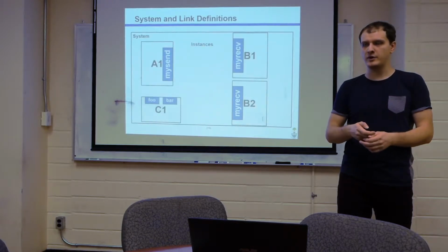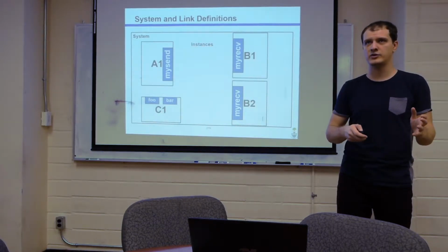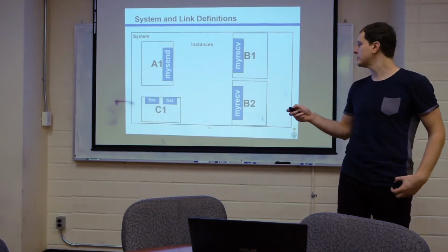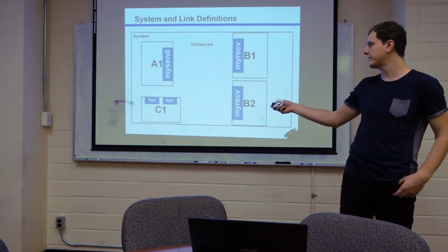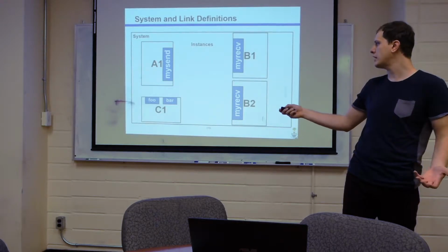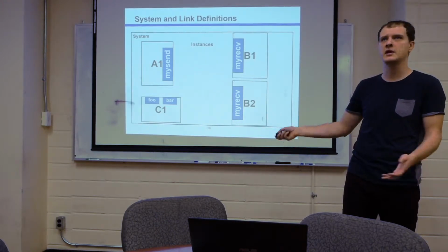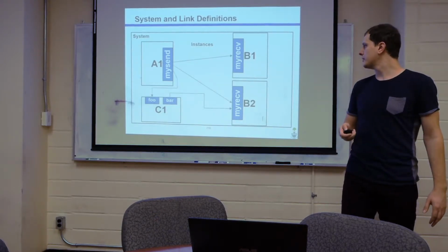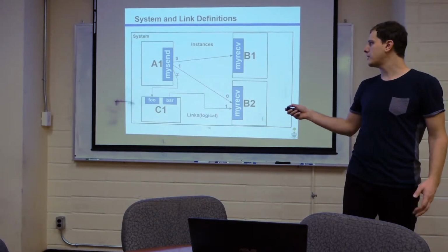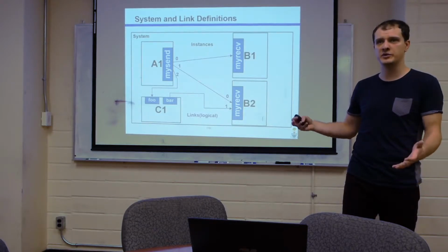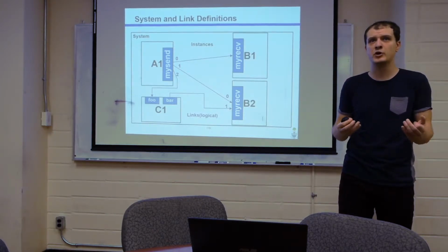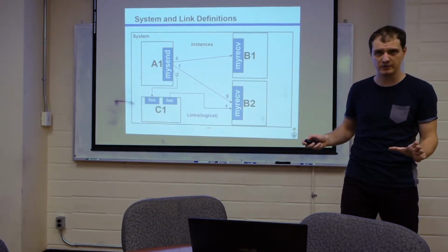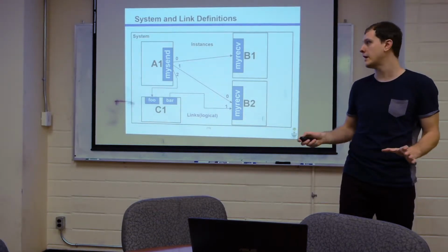Okay, so you define your modules and your interfaces, of which the RS ones are the interesting ones. You define your system, which instantiates the modules, and create logical links between the interfaces. I'm only showing routed streaming interfaces here because those are the interesting ones. So you define links, and optionally, this is when you assign addresses. In Genie, addresses don't belong to a destination. They actually belong to the link. I'll explain that, and that's what lets me do multicast.